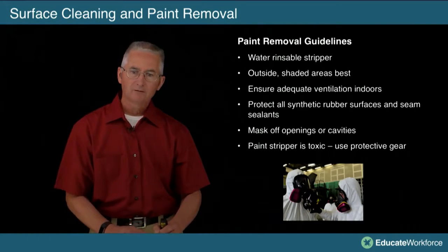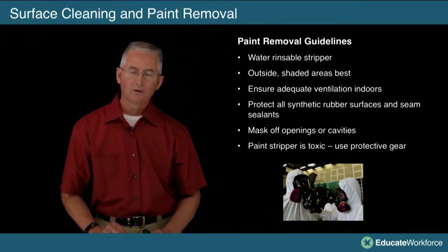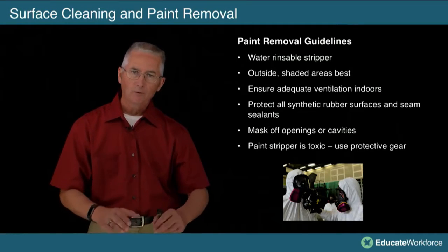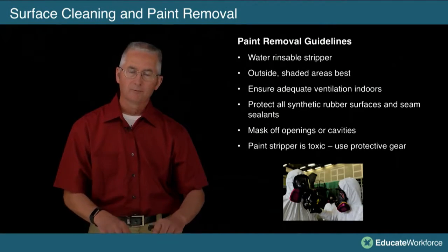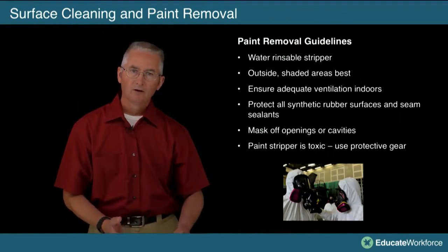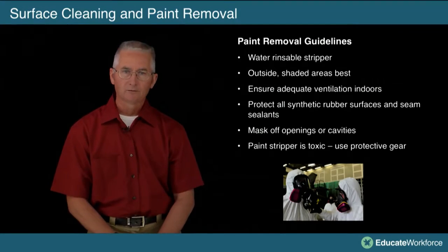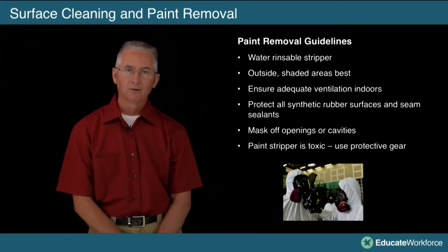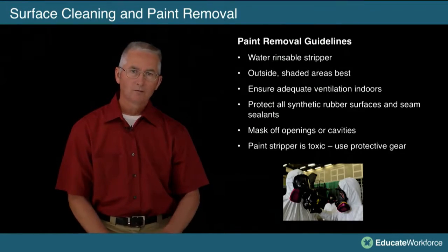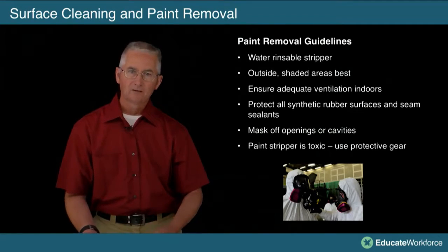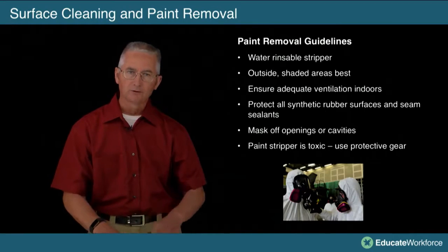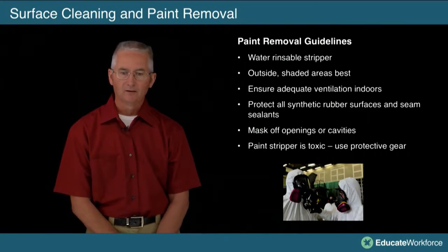So put your paint stripper on, a nice thin coat of paint stripper. Maybe cover it with a plastic to keep that paint stripper from drying. It has to stay moist to work. You may need to apply it 2 or 3 times. Let the paint stripper do its work. Don't rush it. Put it on, let it sit, and wait for the paint to start to blister and buckle. Then go ahead and scrape it off.